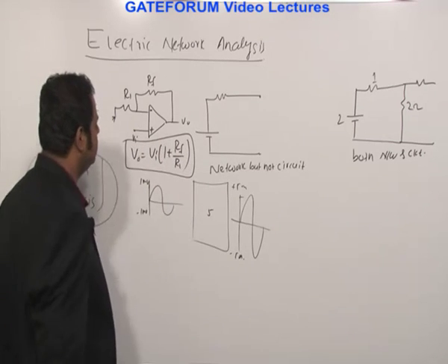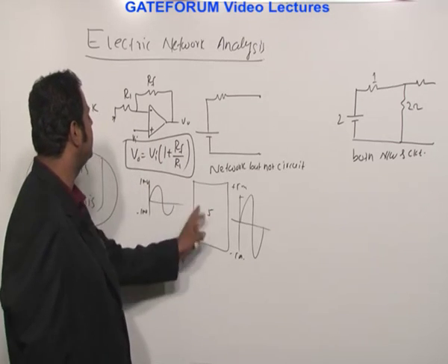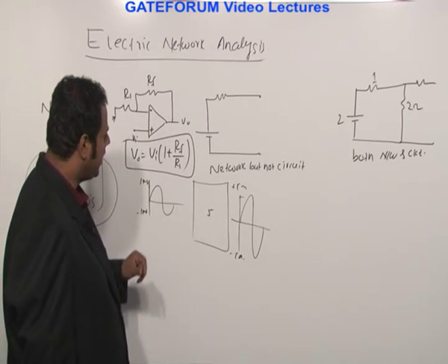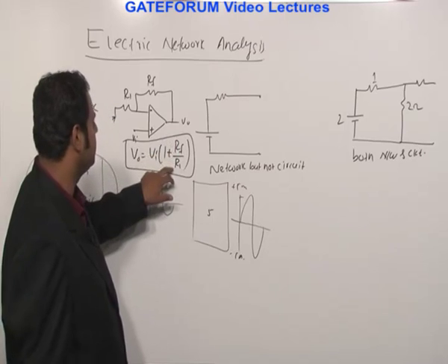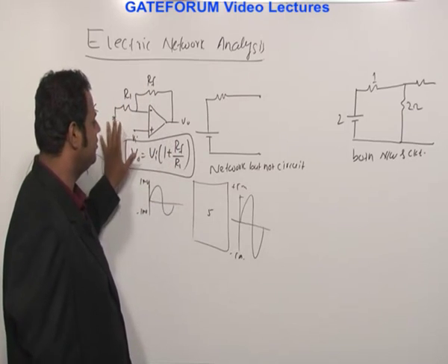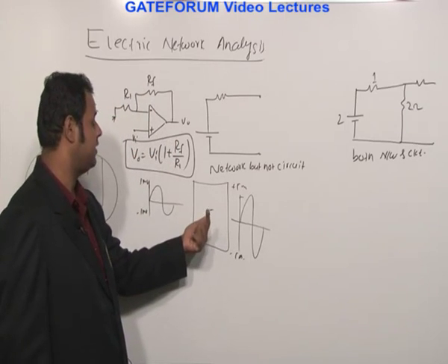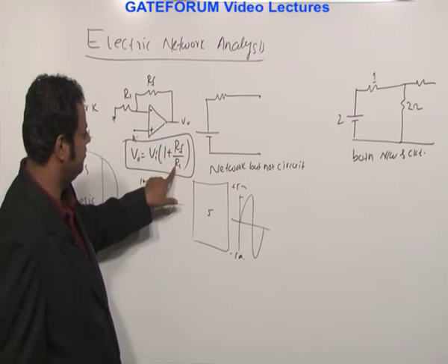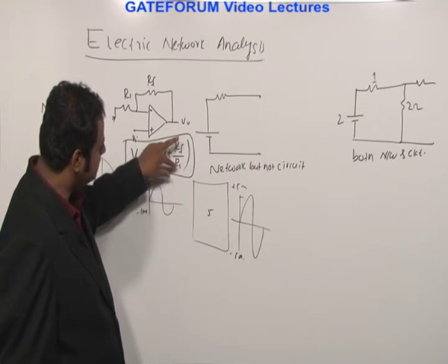So what I want to say is that if I am designing this particular amplifier by using these op-amps, the circuit will look like this. Now I can select the values of RF and R1 in such a way that they satisfy my requirement, the gain has to be 5. That means if this is 1, I am expecting that this ratio should be 4. Now what can be the value of this so that the ratio should be 4?